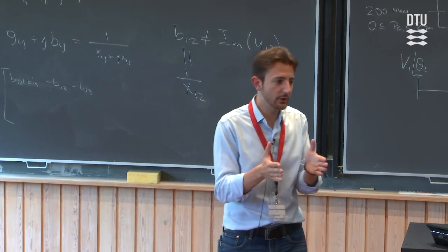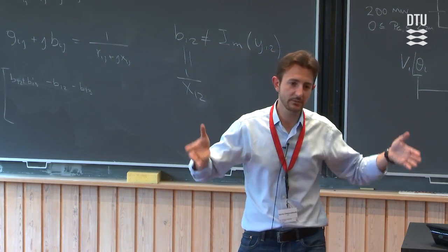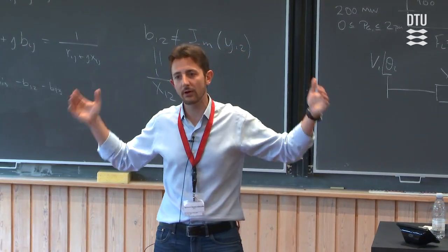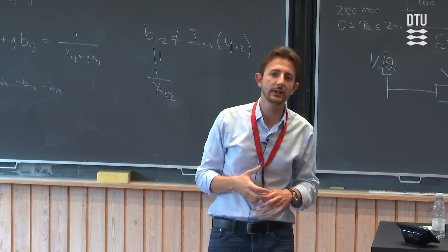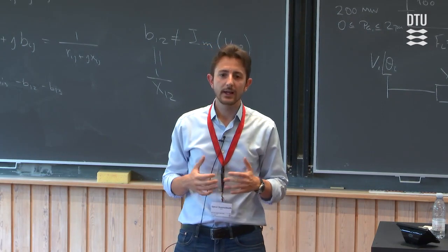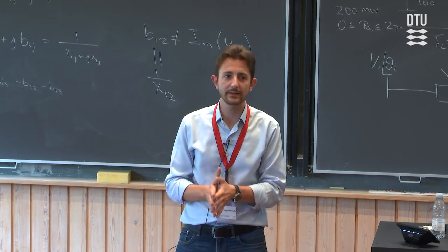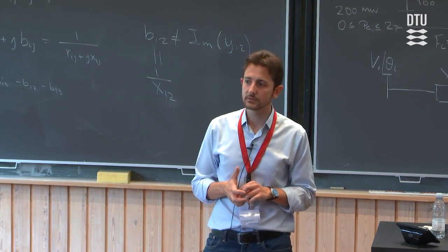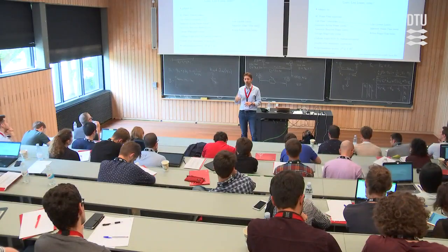If you had already a course in power system fundamentals, then you know that there is a maximum transferable limit between 2 nodes. This becomes a limiting factor when we have long lines. Long lines, like what Miguel said, between northern part of Canada and down to Toronto and even down to New York, or northern part of Sweden down to the southern part of Sweden. In general, for long lines like 500-kilometer lines, the main limit is the stability limit, and this is expressed in active power. In that case, we need the active power flow limits. So it needs some engineering judgment to pick which of those limits you really need.